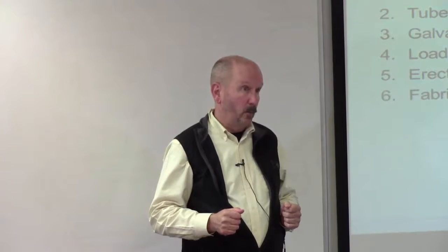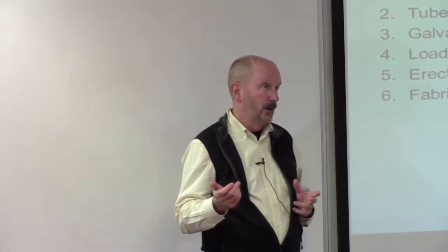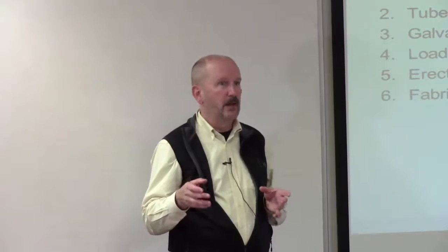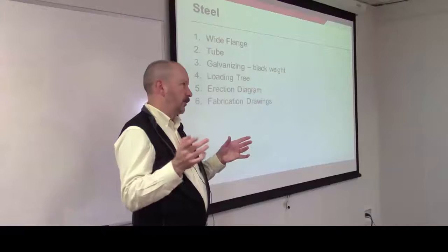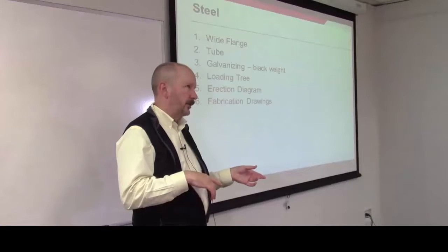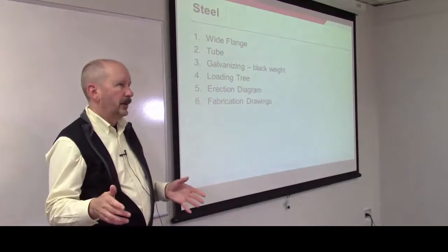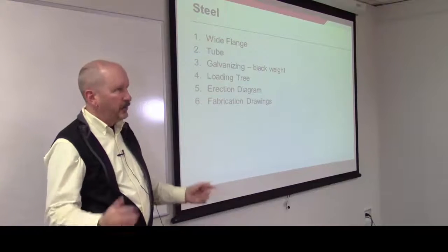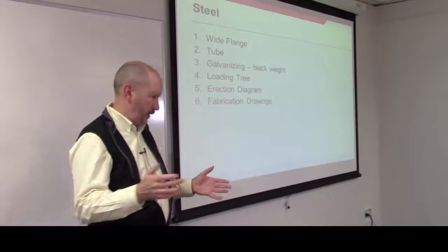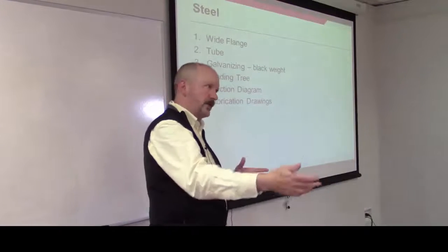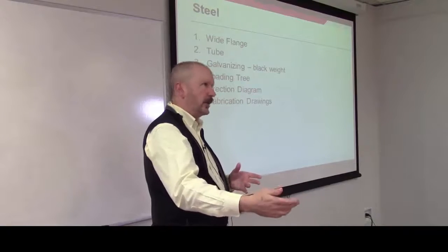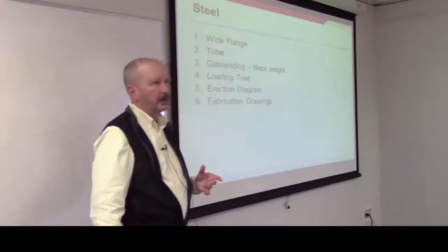Steel is generally purchased by weight, and the purchase price is based on what's called the black weight, which is before galvanizing. Now, there are a few places around that will galvanize structures for you, and their galvanizing pools are not infinitely large. You have to design your structures so they can be galvanized in whatever pool your steel vendor is going to be providing. Most people that do this for a living get used to going to just one or two vendors, and you know what they have to offer. So if the pool is 40 feet long, don't design a 50-foot long member. Or if you have to, know that you're not going to use that pool to galvanize it. Does that make sense?